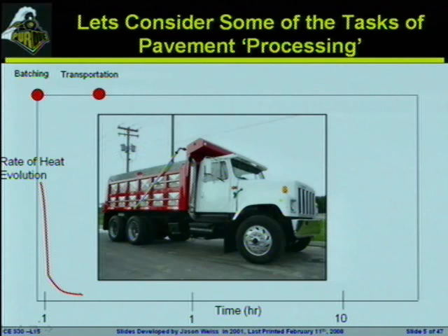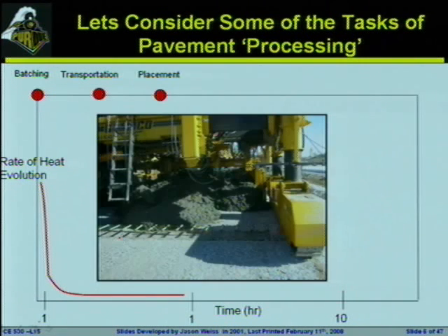What we'll notice is this is where the concrete is really in this dormant phase. The concrete really isn't doing a whole lot. There's not a lot of reaction going on, and this is what keeps the concrete able to be placed when it gets out onto site. We want to be placing the concrete while it's still in the dormant phase, and here you can see it